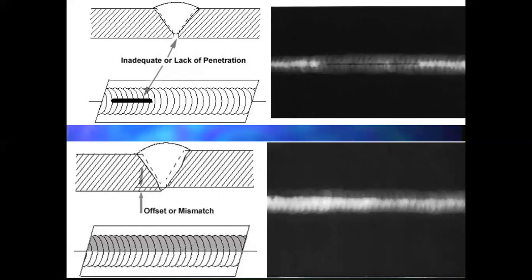Offset or mismatch, it happens. That's a bad fit up. Sometimes it's unavoidable, but in here, it is completely avoidable. We have all the opportunity in the world to set ourselves up nicely in here. So fit up is something I'm always going to be on. Fit up and prep, I'll always be talking about it. You guys will get tired of it until you guys get it all right, and then I won't have to mention it anymore.